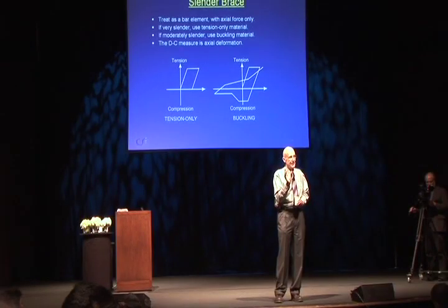But if you calculate an average curvature or an average strain over some finite length, like a plastic zone length, then it's okay. And we'll talk about this in the next session because this becomes very important for shear walls. Because in shear walls, you may quite likely use strain as a demand capacity measure, but you have to define your gauge length very carefully. It's not just any old strain, it's a special strain over a special gauge length, and we'll talk about that later.